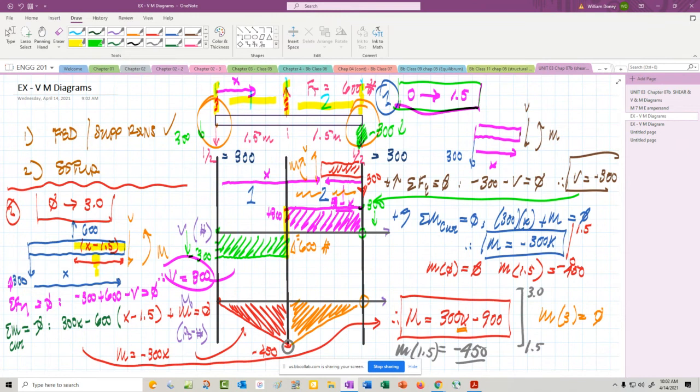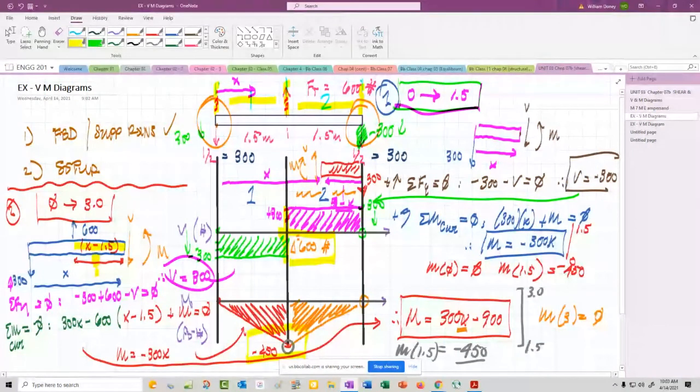So looking at that, if we were looking to design or tell our designers what to use, we'd have a max shear of 600 and a max bending moment of 450. And they would occur right in the center, so they would need to know to design it thicker there or bigger, more robust at those points.